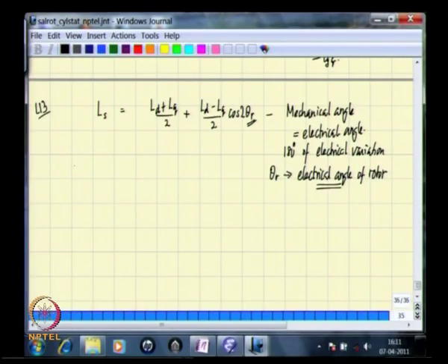The second one, we notice that the MMF waveform that we took was the fundamental component of the actual MMF waveform, and in trying to determine the flux generated by the MMF waveform, we are assuming that the flux crosses the air gap and connects with the rotor as well.